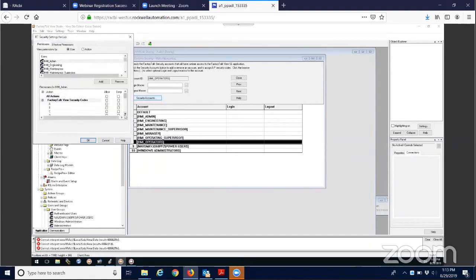With the newer release, you can now do it as part of user groups and areas. It's still heavily tied to your domain, so from a Windows point of view, you let IT handle the domain, usernames, and passwords, and everything propagates all the way through the FactoryTalk side of it. But now you can set up your rules where it's not specific to the codes. You can actually do it by the type of role that person has.